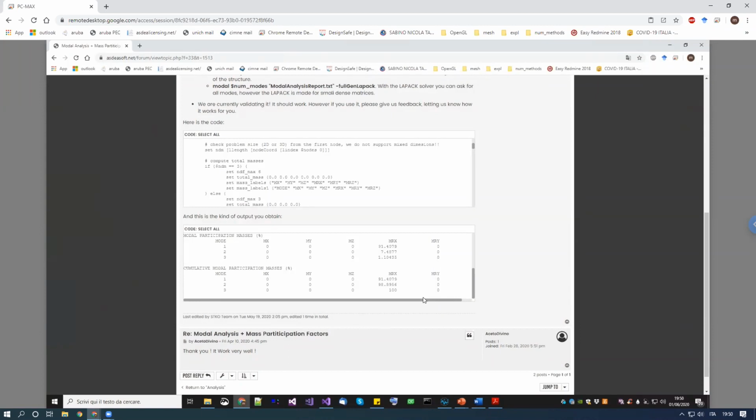Well, actually, it may happen if the master nodes are not aligned in a single line, okay? So, for example, let me see if I can annotate something here. Let's say these are two slave nodes of a floor, and here you have the master. Then you have a second floor, which is here, here, and for some reason, the master is here. In this case, yes, this slave will be nearer to this master rather than to this one.